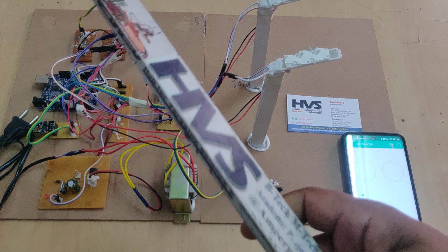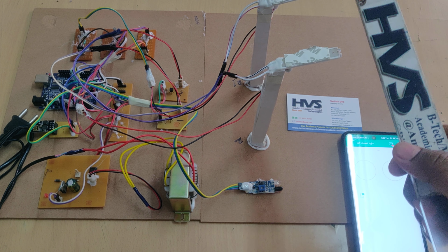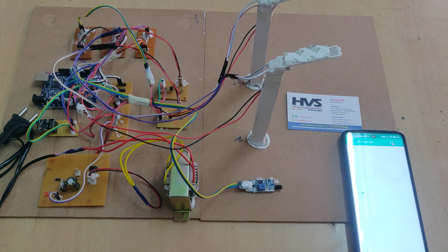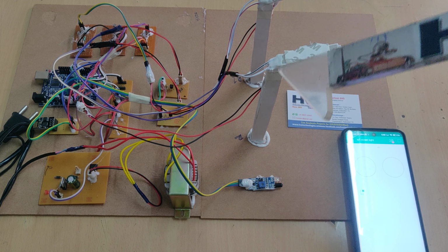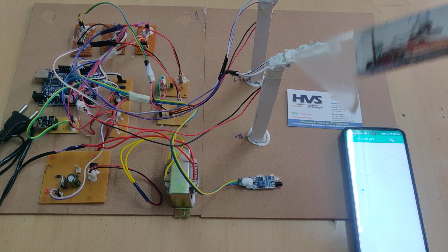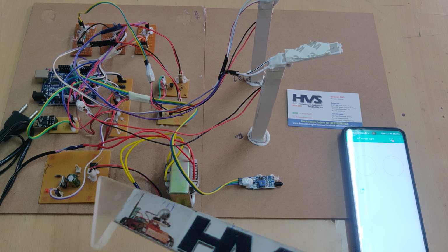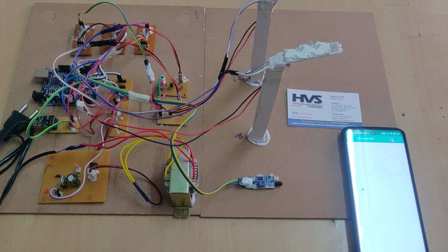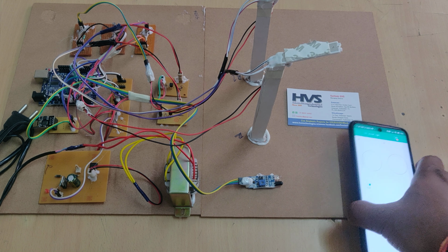Based on the LDR input, if night mode is detected, then only 50% of the brightness is provided to these two street lights with the help of the two transistors. In the night time, if any vehicle is present, then full brightness will be provided to these street lights. In this switching sequence, if any street light develops a fault, then this particular LDR will inform the microcontroller, Arduino Uno, about the fault in the respective street light. That will be intimated to the Blynk application with an alert notification. Even if you haven't opened the app, you'll get the alert notification on your mobile phone.